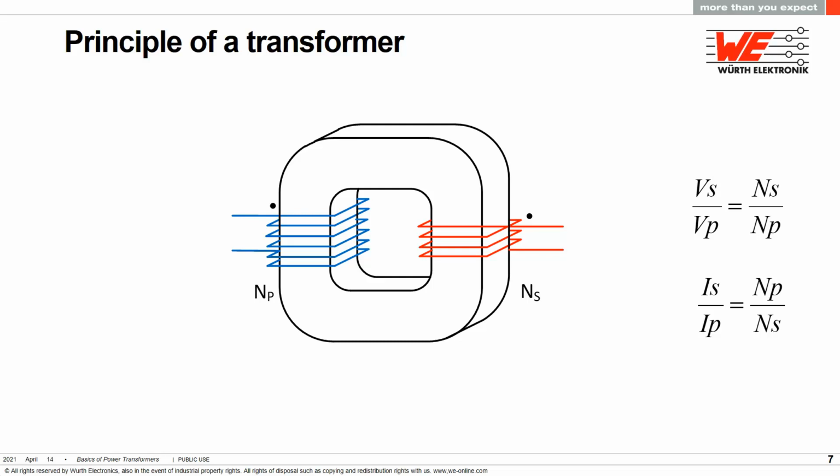The little dots which you see on schematics are called polarity dots, and they indicate the polarity of the winding. The dot end of all windings have the same voltage polarity. This helps you to connect windings in series or parallel if needed.